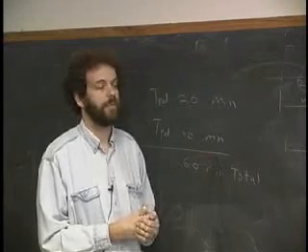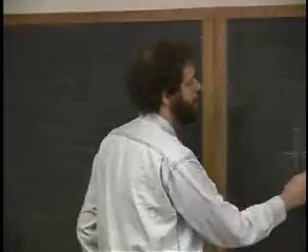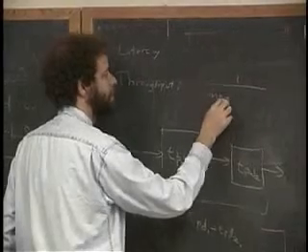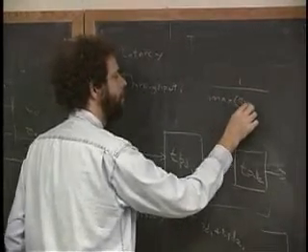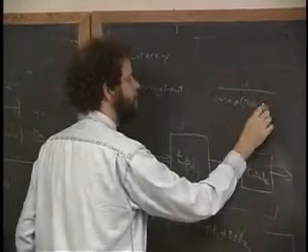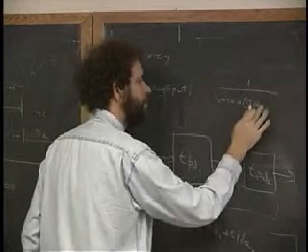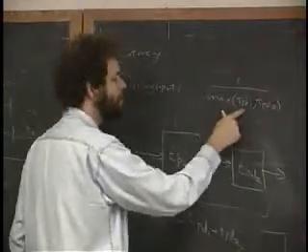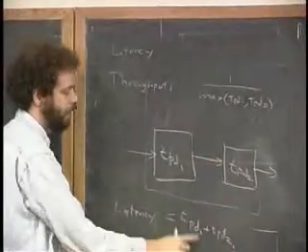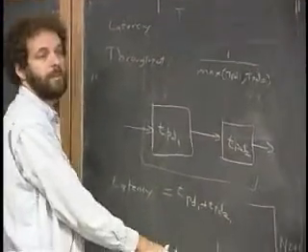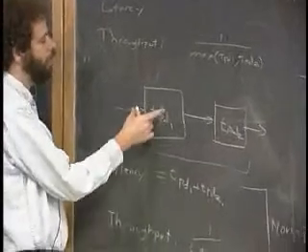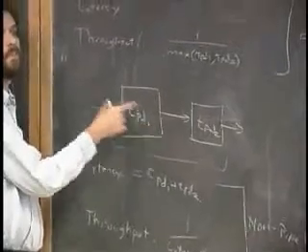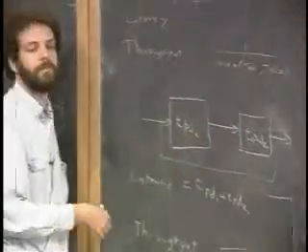1 every 40, right? So it's actually, if we have a combination like this, it's 1 over the max of TPD1 and TPD2. And this is an improvement over 1 over the sum of TPD1 and TPD2, which we had before. Because we just look for where the slowest element is, and that's the one that sets the maximum rate at which things can go through.